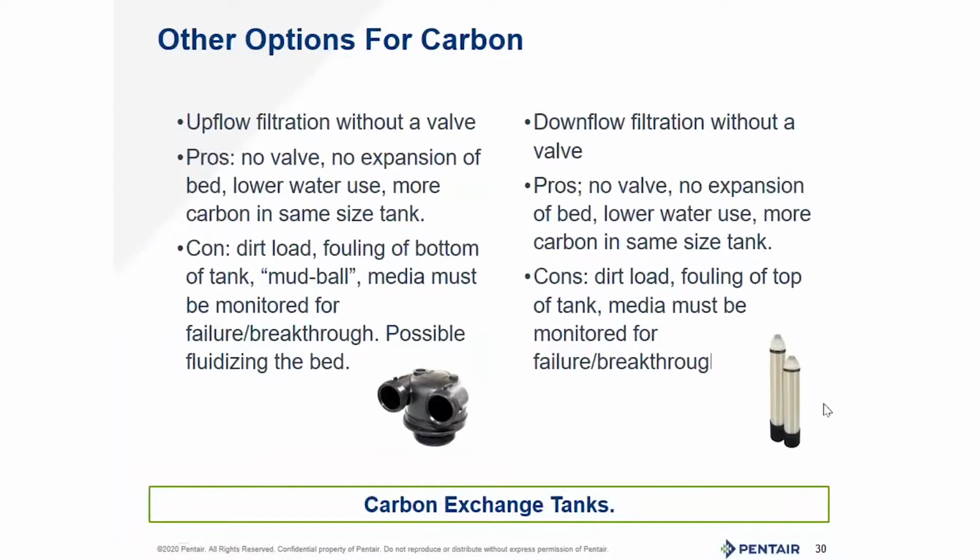Okay, but upflow without a filtration valve can be done on these tanks. The pros: no cost of valve. There's no expansion of bed because you're going to be filling that entire tank with carbon. There's no freeboard there. You have lower water use because you're not backwashing. More carbon in the same tank.